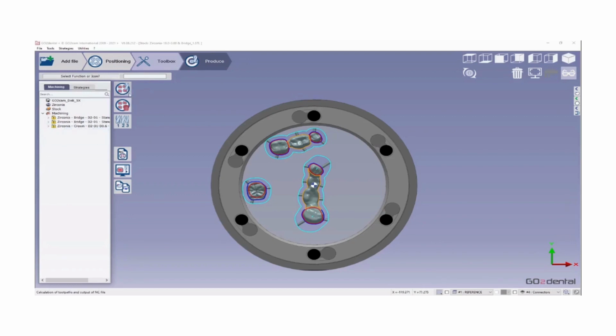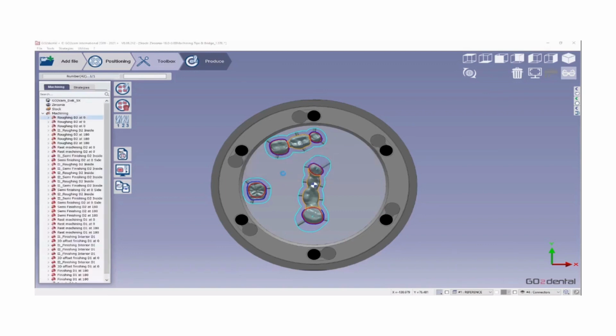Coming to these commands here, the first one calculates the toolpath as well as generates the file info. So we click on it to launch the calculation of all the strategies. First we define a name for the used blank, which we can load again for next production. Then validate. While it is calculating, we see a dialog showing the progress, with the first of 40 cycles being calculated. We can also stop the calculation anytime.